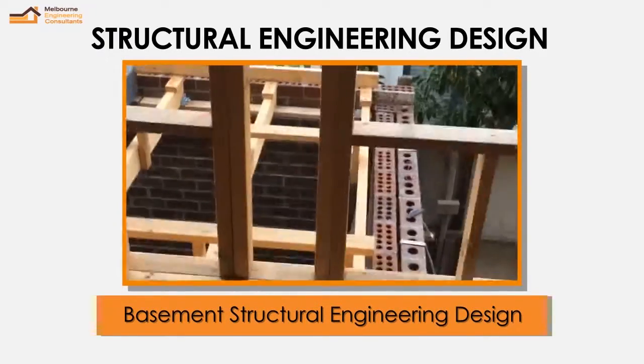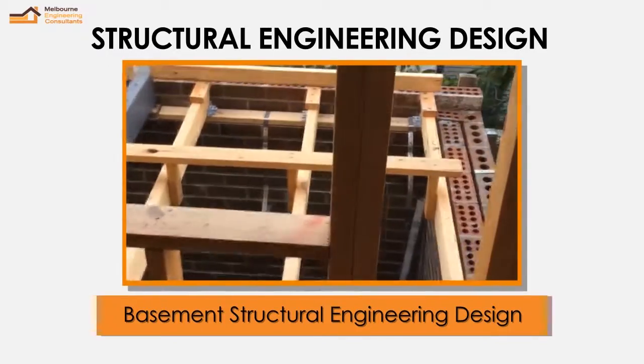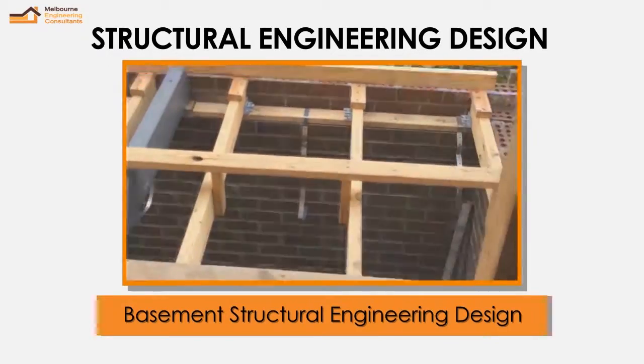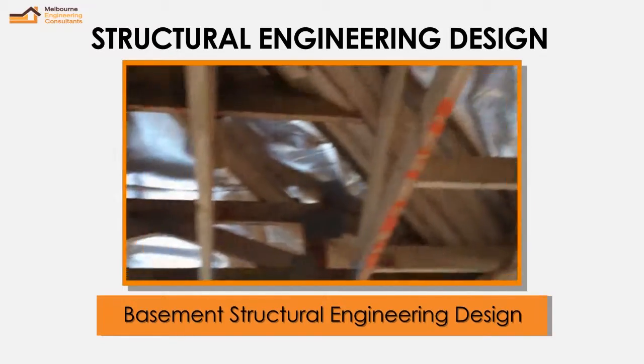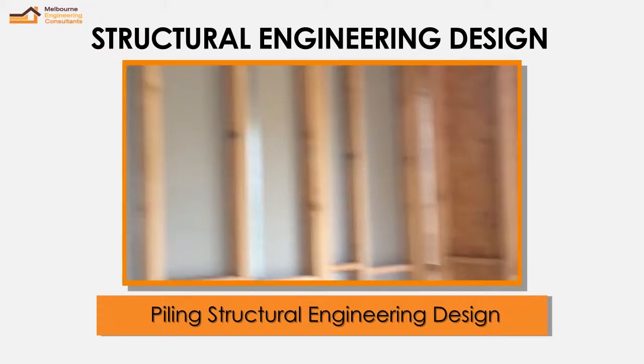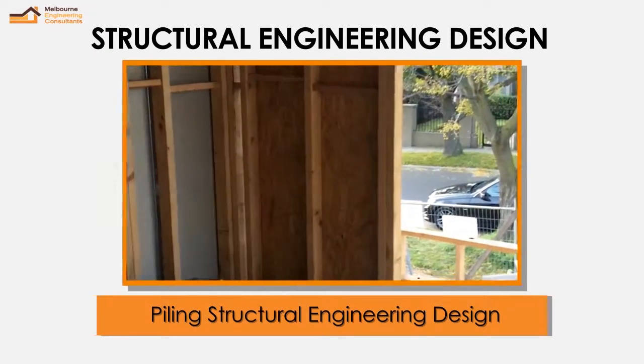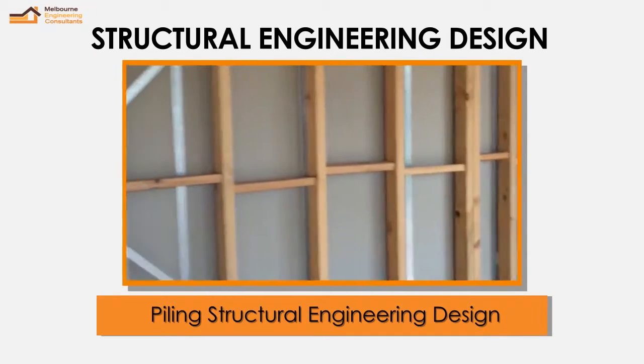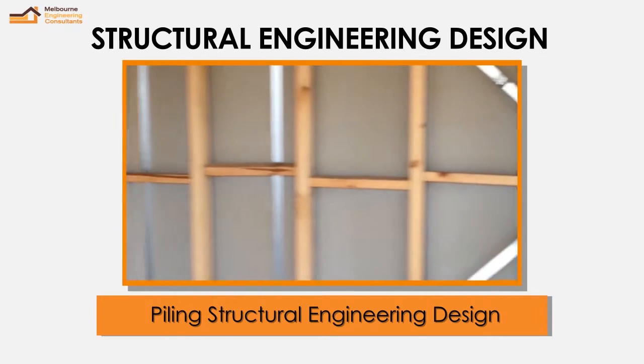Here this is showing the external roof with the roof rafters at 600 centers and one steel beam which is picking my this side. All internal walls are non-load bearing, only the load bearing trusses are transferring the load from one end to the other end. So internal walls are just non-load bearing.